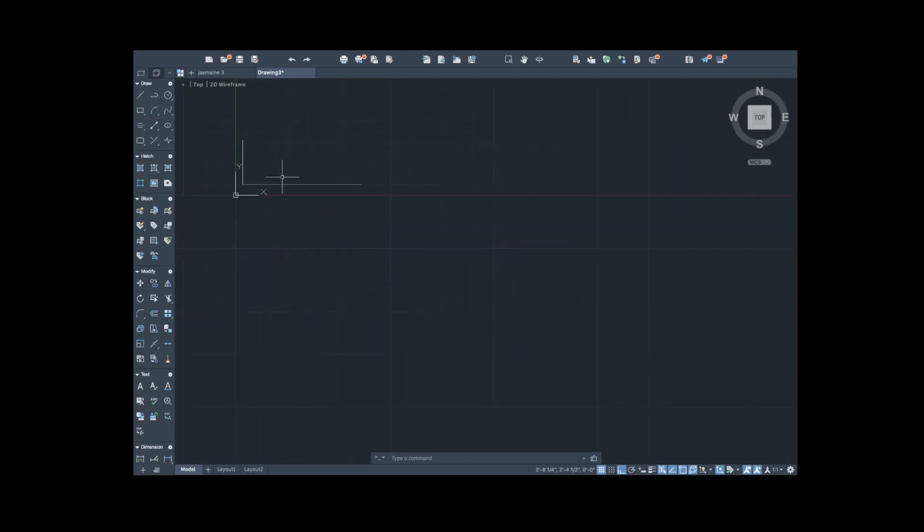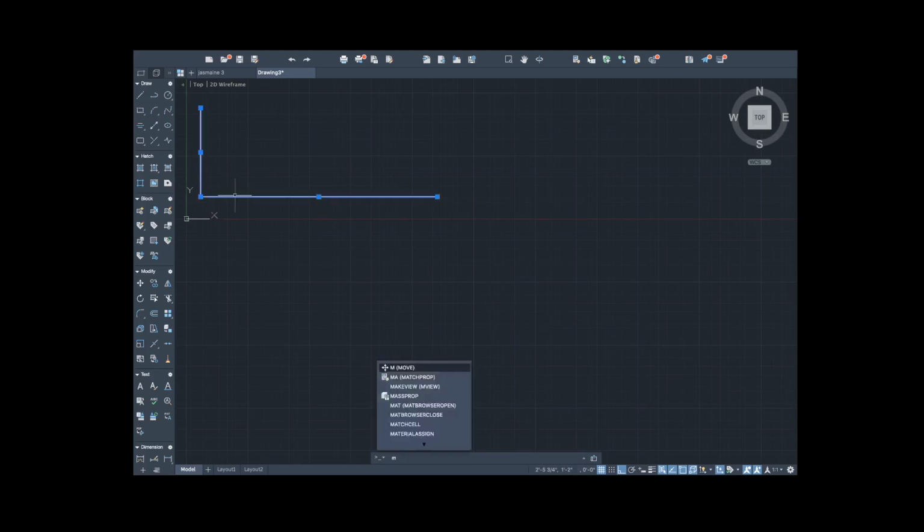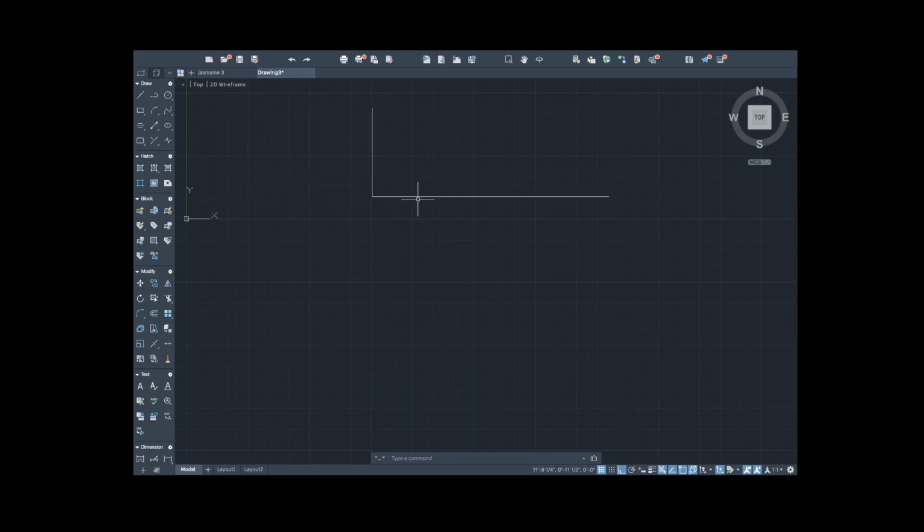Escape. We're gonna do the next side. Let's move the drawing. Type M for move. Specify base point. Let's bring it closer to right here. Okay, let's press escape for escaping the command. You have to use a mouse to draw. Okay, it's more convenient. Click on line.